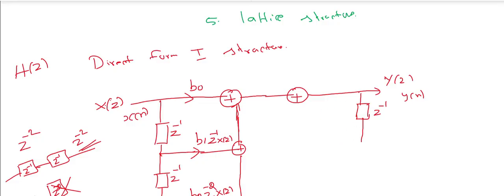So this is an all pole system. Okay, I can represent this as an all pole system, z minus 1. Now 1, this is a 1. Okay, always it is 1. So 1 minus a1. Minus a1. So this is another all pole system. I put minus a1, so minus a1 z inverse unit delay element into y of z. This is a feedback system.